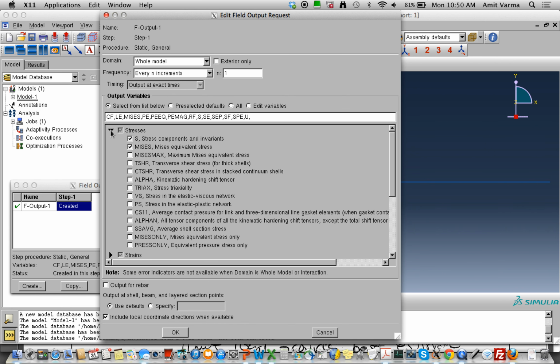Right? But I don't have an axial force, so I can have U1, U2, and UR3. Both ends are fully restrained in the initial step, and of course that's propagated. Hey, I left U1 equal to 0. How about that? I was thinking about applying an axial force. That's what it means, but I hadn't applied it yet. For the case of axial force equal to 0, it's not going to matter. And then the loading, in this case, I've applied the loading at the same location.